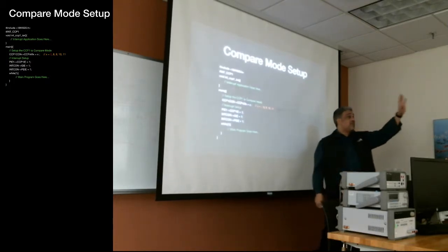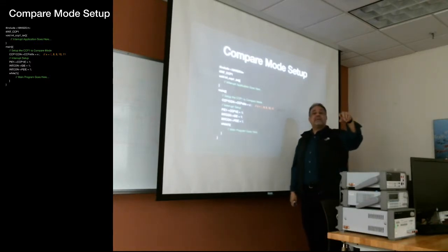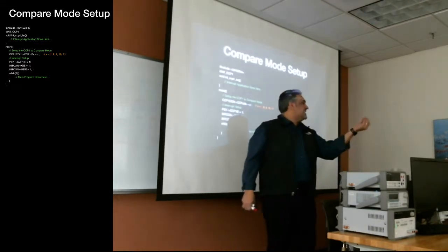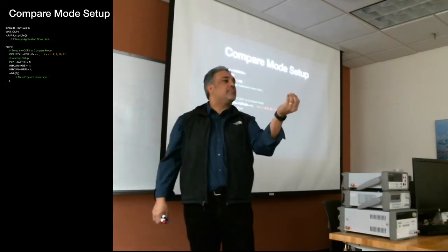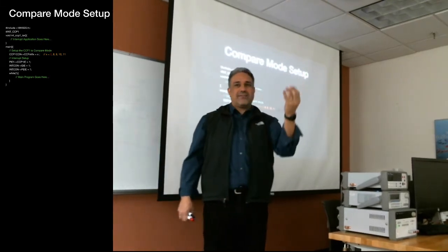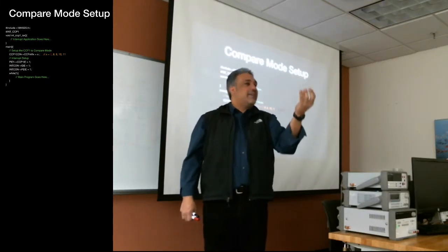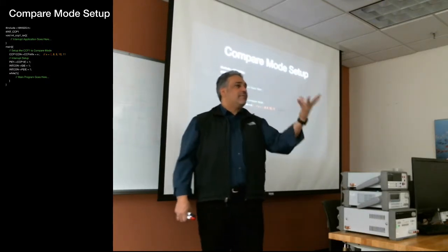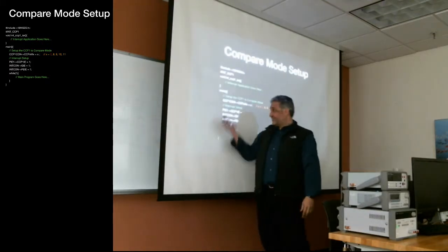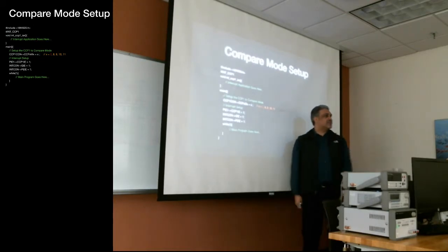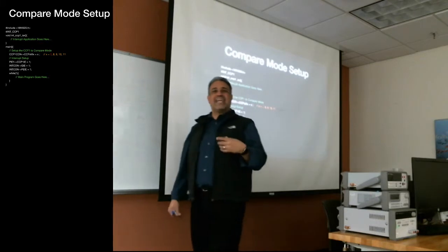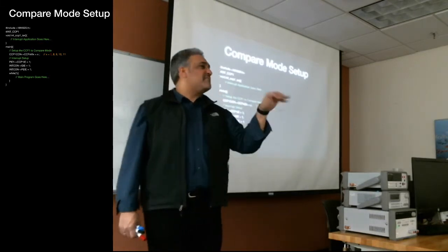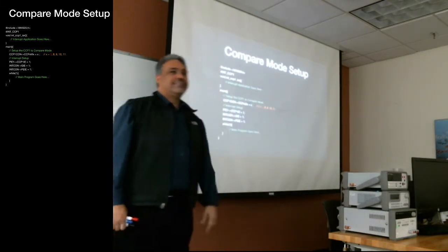By the way, if you see how the LEDs in your PCs behave as if they're a heartbeat, or they fade away and come back, and fade and come back, how do they do it? Compare mode. They simply use compare mode and switch around the values of CCPR to create a breathing or fading LED effect. That's how they do it.